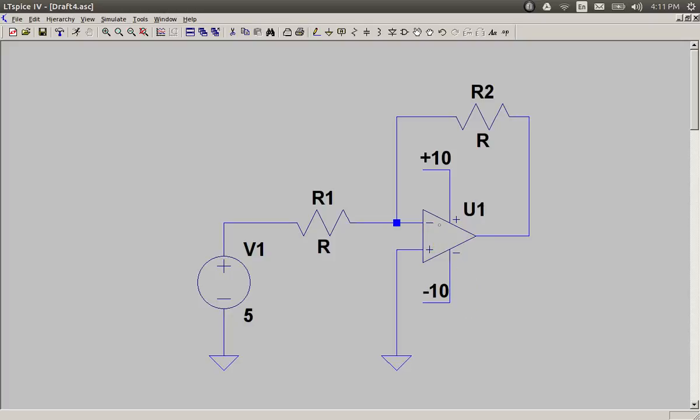So this is an amplifier in negative feedback. It means that the output is fed back to the input at the minus terminal. So in a real op amp, you have a voltage here. The amplification A, that's the gain of the amplifier, could be, let's say, 1,000,000. Let's say this is V plus and this is V minus.